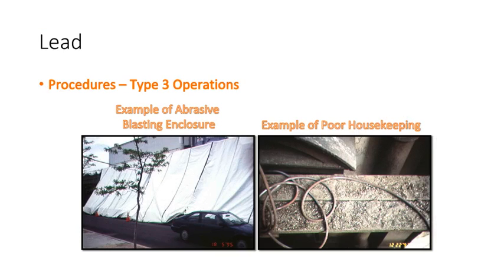Type 3A operations include welding or high-temperature cutting of lead-containing coatings or materials indoors or in a confined space. Burning of a surface containing lead. Dry removal of lead-containing mortar using an electric or pneumatic cutting device. Removal of lead-containing coatings or materials using power tools without an effective dust collection system equipped with a HEPA filter. Removal or repair of a ventilation system used for controlling lead exposure. Demolition or cleanup of a facility where lead-containing products were manufactured. An operation that may expose a worker to lead dust, fume or mist that is not a Type 1, Type 2, or Type 3B operation.